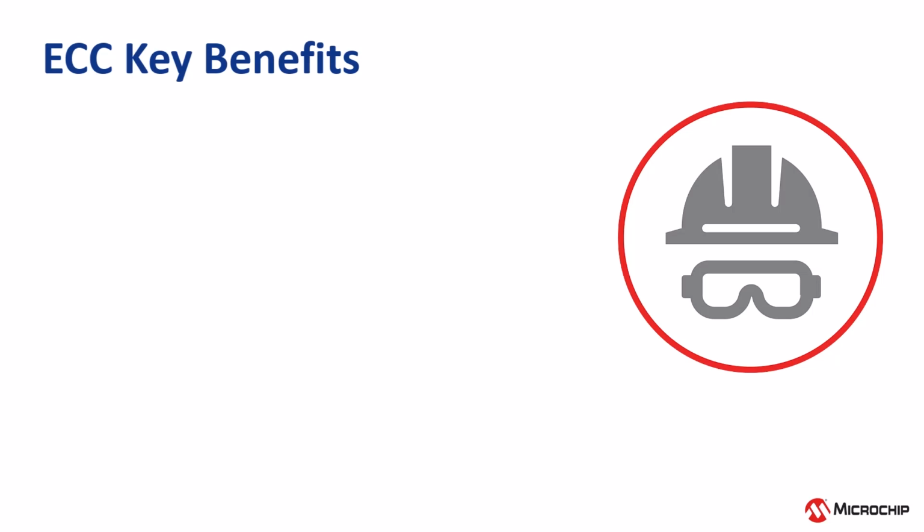Now, we covered how data corruption can present risk or cause harm earlier, but let's return to that idea and talk about why SecDed ECC memory protection is important in certain applications. Generally speaking, ECC protection is a versatile tool for any safety-critical application since it prevents silent memory corruption over time. But to be more specific, it's especially common in automotive, industrial, aerospace, and data center applications. But regardless of where it's used, ECC's protection provides multiple key benefits.